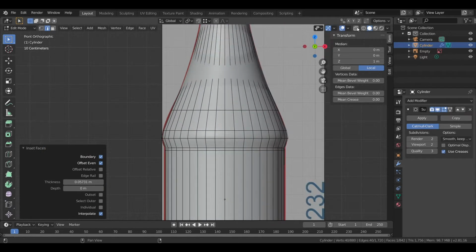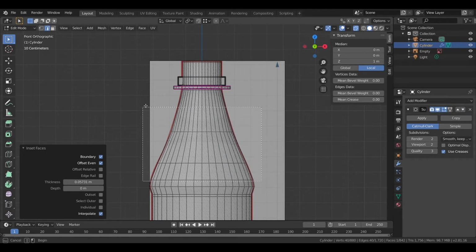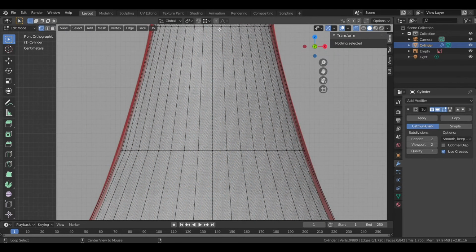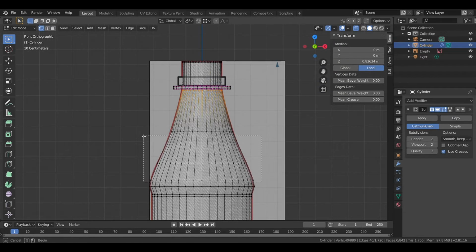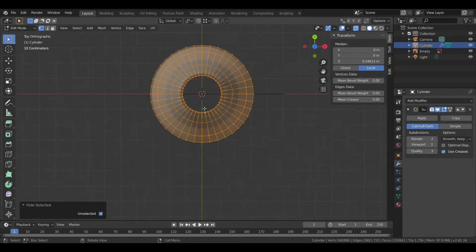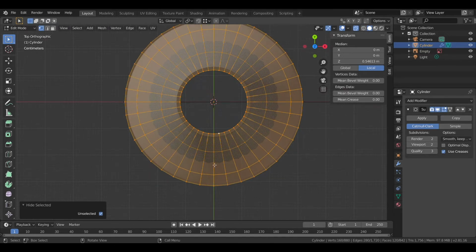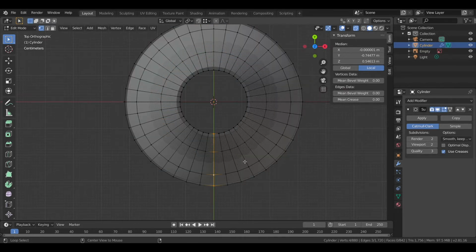In some parts, the bottle remains cylindrical, but in others, it deforms according to this polar symmetry. For example, between the neck and the label part of the bottle, it repeats its shape 10 times. So in this case, I selected 10 equidistant parts and I was scaling them along the X and Y axis.